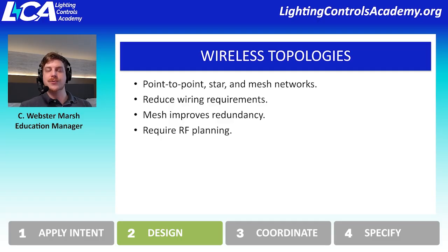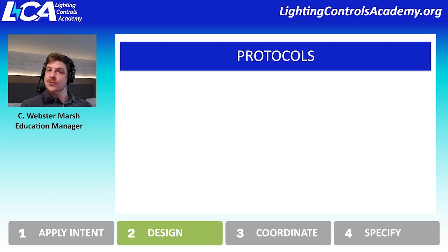If we're using the same radio frequency channel as that Wi-Fi, we can have what's referred to as data collisions, which create issues with communication or even completely halt communication on a wireless system. So we want to make sure that we're communicating with all of the appropriate groups that we're using a wireless signal, and that we're not going to create any issues or find any collisions within the systems.